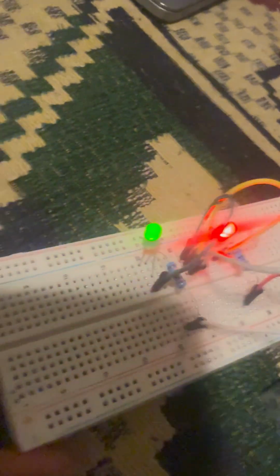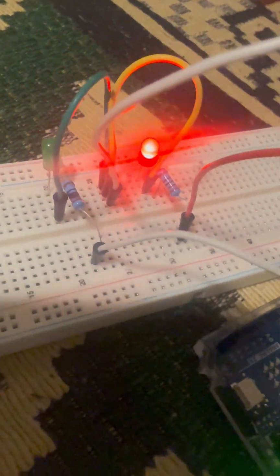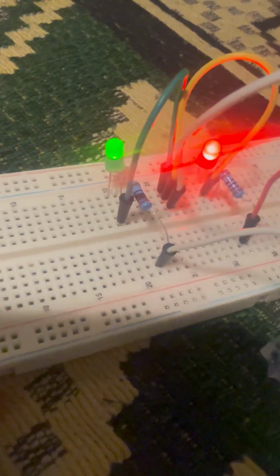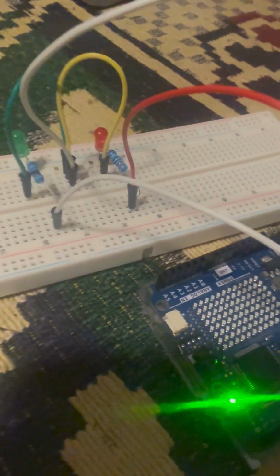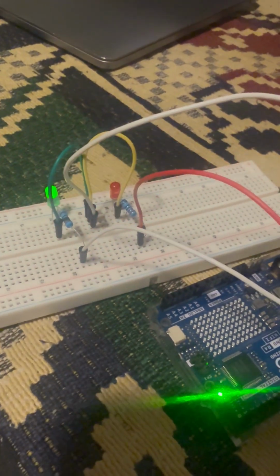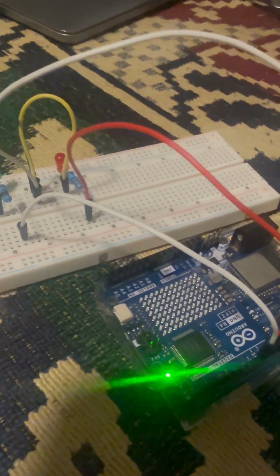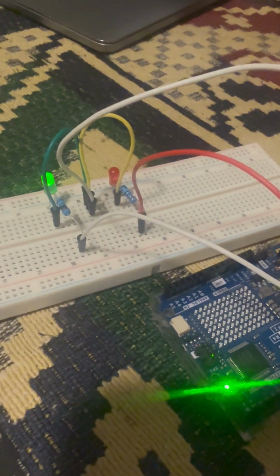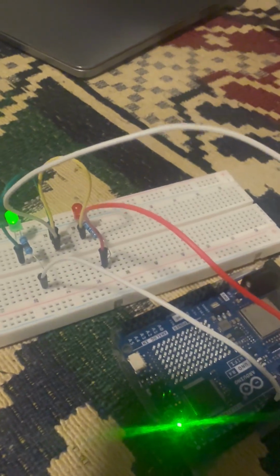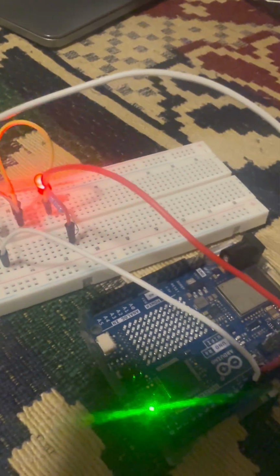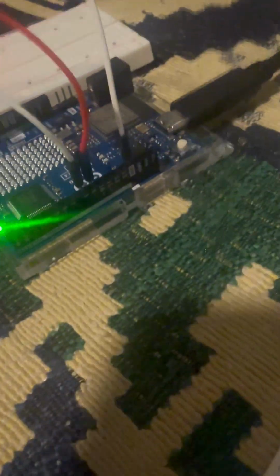If you want to see a better view of the circuit itself, here you go. Make sure that you're using 220 ohm resistors. If you want, you can use a 330 ohm resistor. But if you go below that, it's going to let through too much current and your LED is going to burn out. If it's bigger than that, you're going to let through too little current, so your LED won't light up at all. And here's just some wiring, the big one to the middle, just like that.